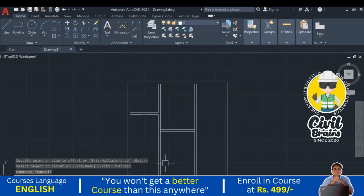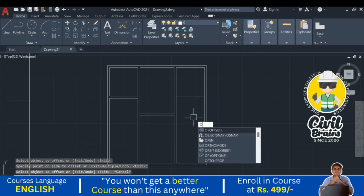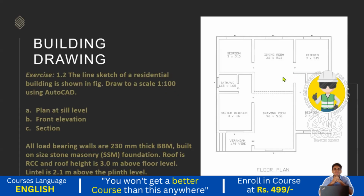Okay, so this room you have decided. Next, this one is also 3.15. You just go to the offset, press enter. The room depth is 3.15, press enter, offset, press enter. Then the wall thickness here is changed. I'll just show you here. This is a partition wall. Here it is not mentioned as a partition wall, but here it is mentioned as a partition wall, so that depends on that. But in this plan it is mentioned as a partition wall, then we need to take the partition wall only.